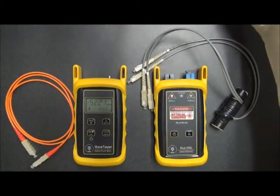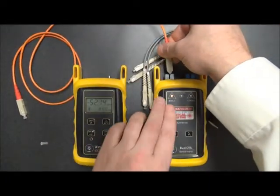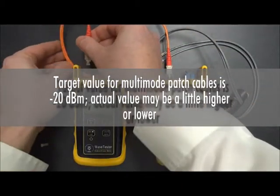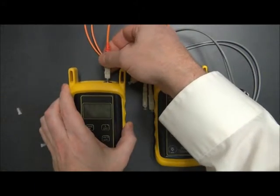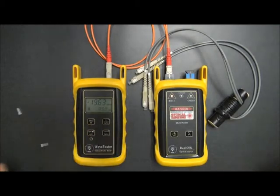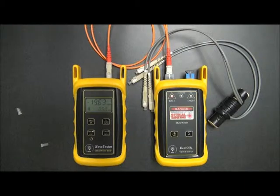Now, when we are looking at the power level through a patch cable like this, our target value is going to be around minus 20 dBm for multimode. It might be a little higher or a little lower, but it should be relatively close to minus 20, and we definitely do not want it to be any lower than minus 21. Now that is for 62.5 micron cables. You'll have different results for 50 micron.